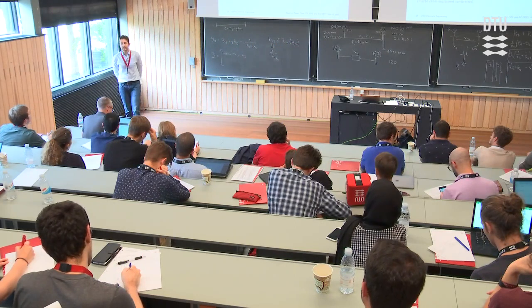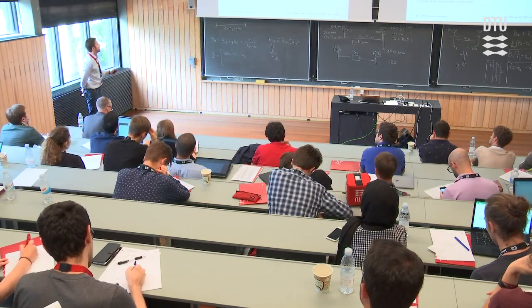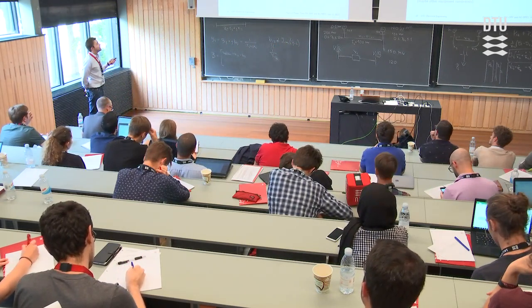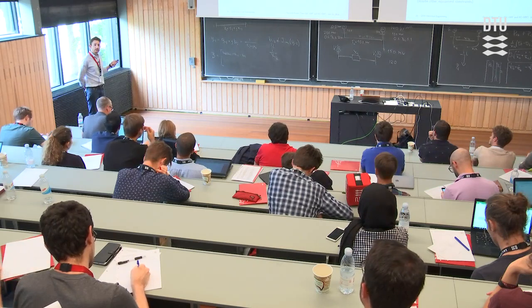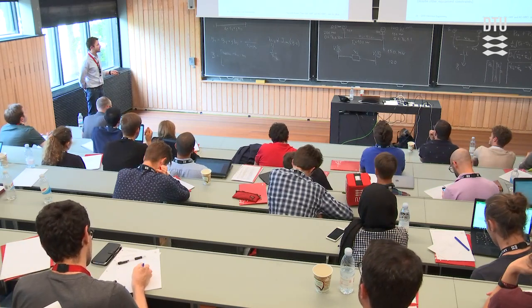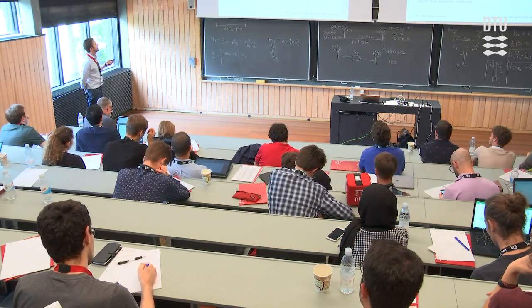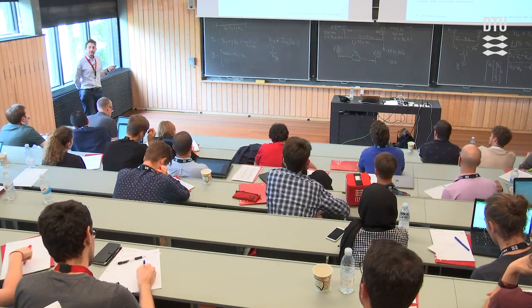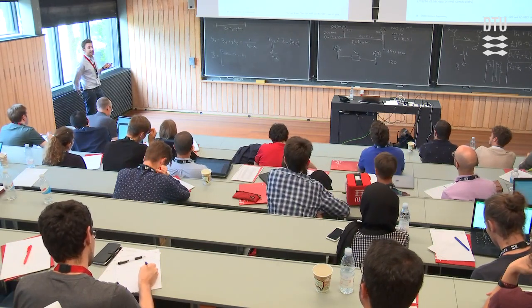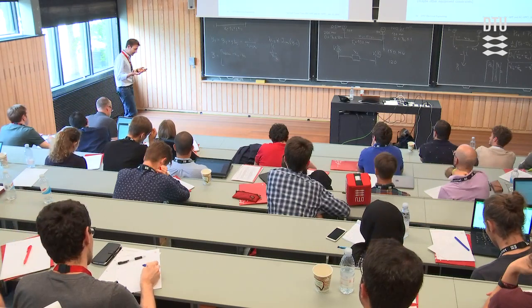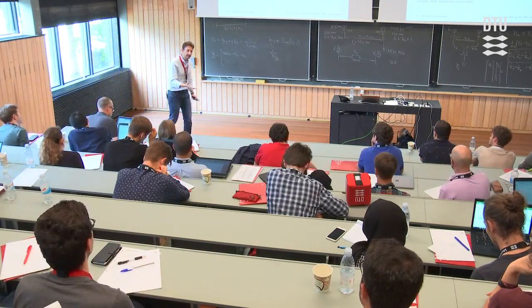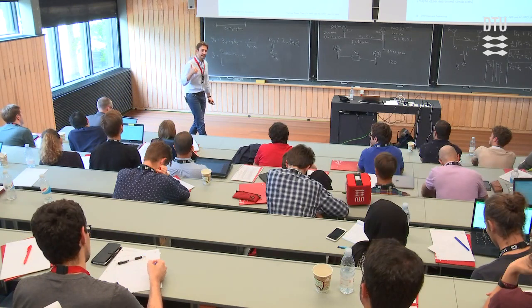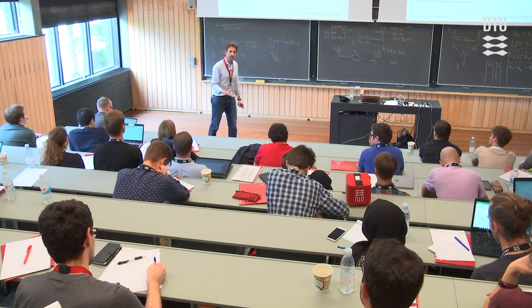And then we have the constraints. So we have the full AC power flow equations instead of the linearized ones that we had here, right? We have the line flow constraints. The difference with the DC-OPF is that we have active and reactive power, voltage magnitude, and voltage angles. Okay?